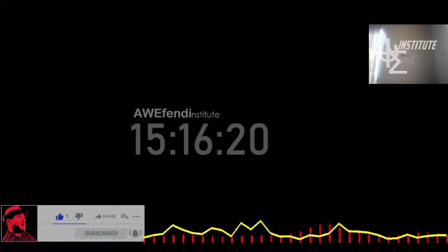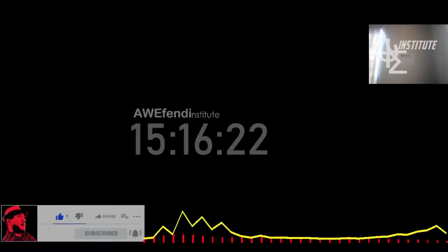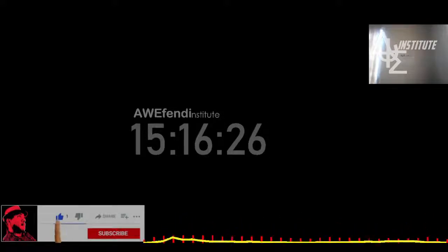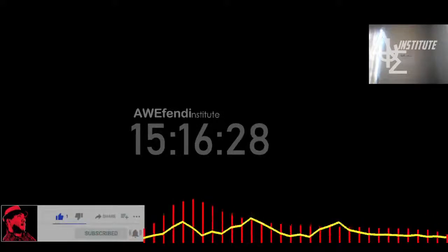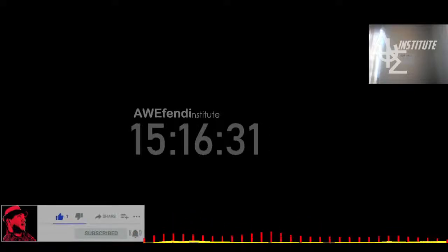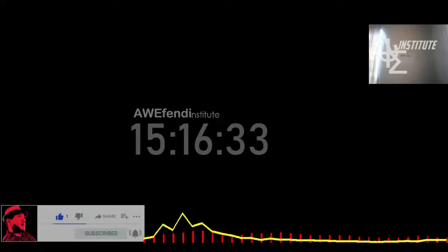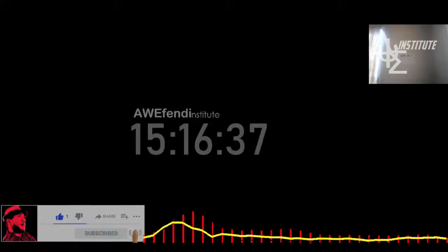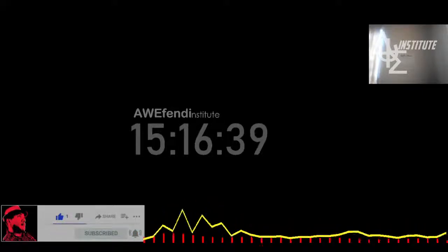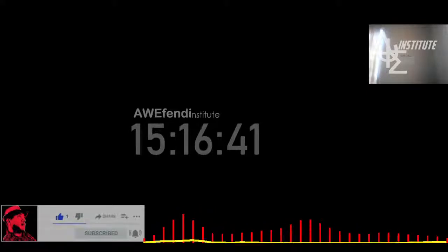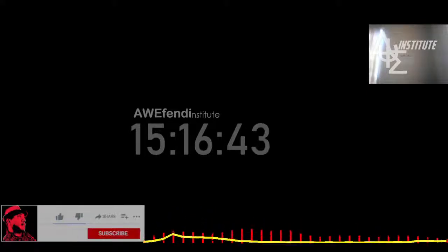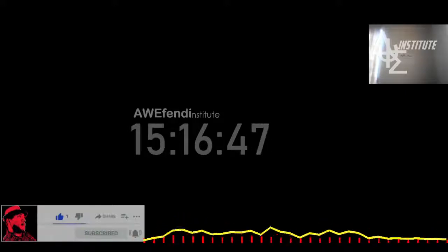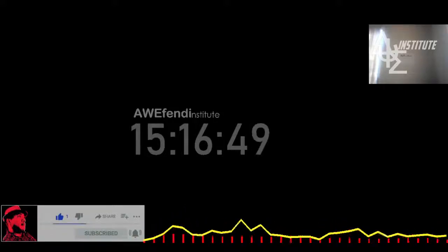So let's start the calculation and see if the maximum temperatures are lower now, and hopefully around a more reasonable value that won't melt everything. So here we have, as you can see, we're around 75 degrees Celsius. We can look at the outer temperatures. If you hover over a certain location with your mouse, you get the exact value on the color scale. So here you can see the top IGBT is indeed the hottest component. It's around 75 degrees Celsius.